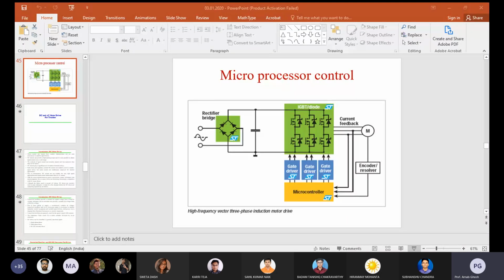Suppose you are fixing the speed of the motor, so you have to give some reference value. But it's not possible to give it in RPM. So what you can do is give it as an equivalent voltage value or any other set value, it may be in terms of gain or other terminologies. So you have to fix the set value.